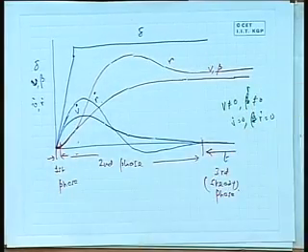So, I can go to my equation of motion and try to find out, because it will be very simple, since the equation of motion will have only v and r. So, there will be two equations. If you recall, my earlier equation has something v plus something v dot plus something r plus something r dot equal to something. But here I will have simply something v plus something r is something, something v plus something r is something. So, I can solve for v and r very simply. I will not solve it, but I want to show you the solution part.